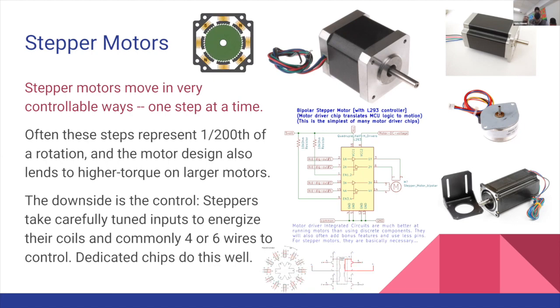And it's what happens when you have the coils of wire inside of a motor. There's always a permanent magnet and a coil magnet. The brushes are needed if the coil is on the spinny part, because you can't just wire it in, because it won't be able to spin forever. It can only spin until the wires get snug. So a brushless motor solves this problem by putting all the coils on the outside of the motor body, and then the inside piece, what rotates, is the permanent magnet. That arrangement is really cool, but it means that your motor drivers need to be more complicated.